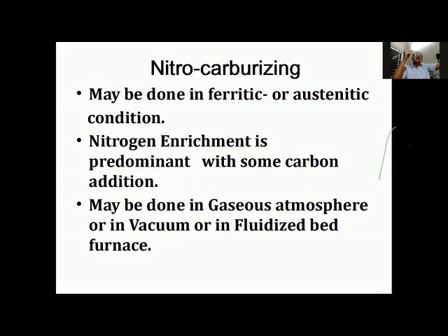The typical nitride layer is between 8 to 15 or even 20 microns, depending on the application. Many times, this is followed by steam bluing or other treatment for increased corrosion resistance and improved surface appearance.